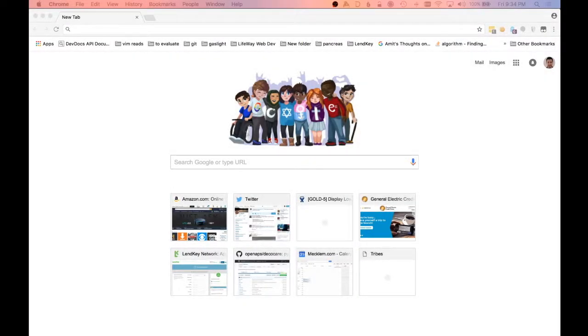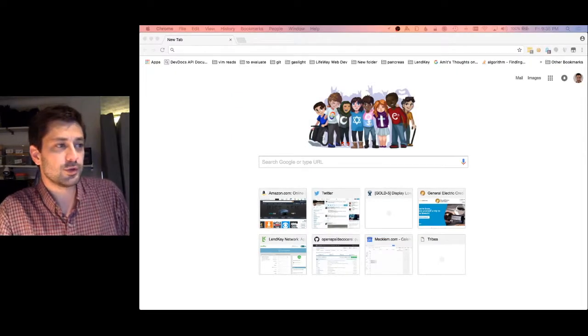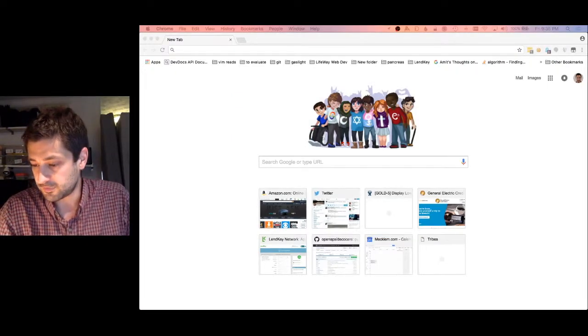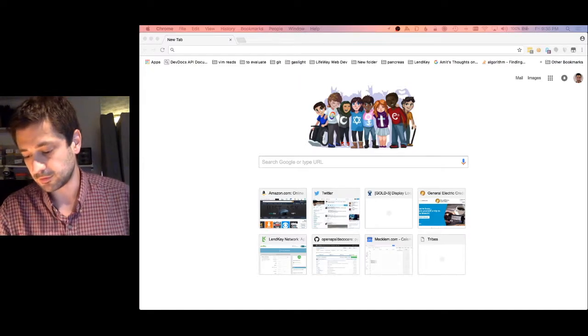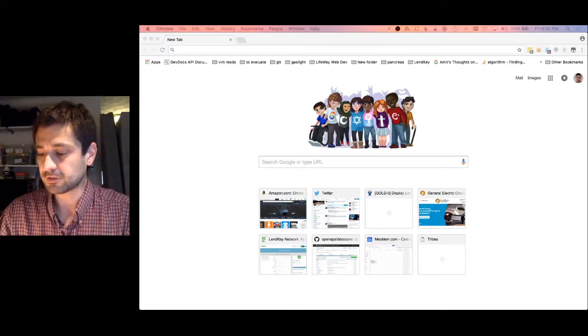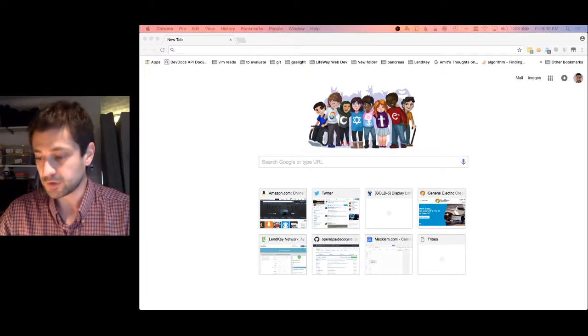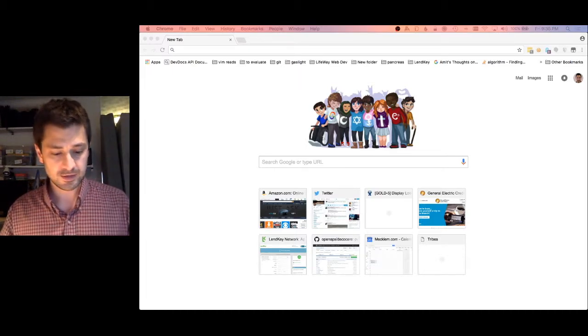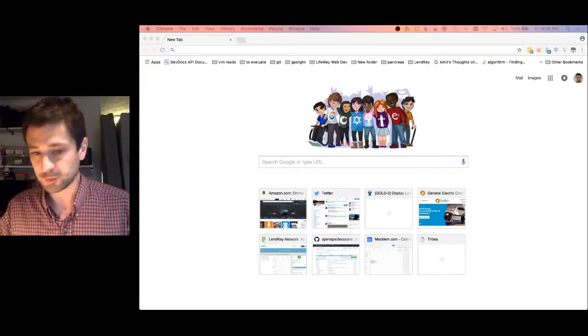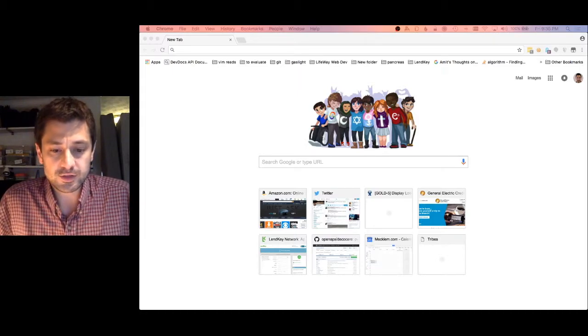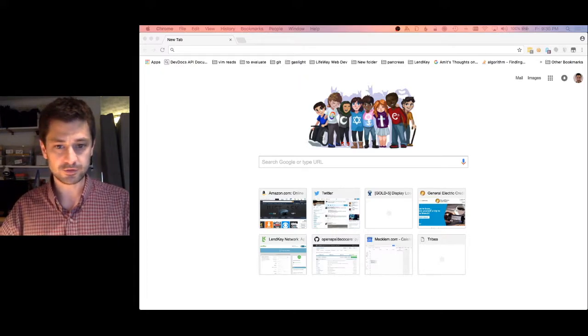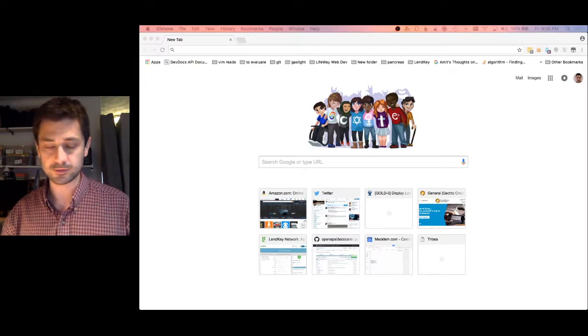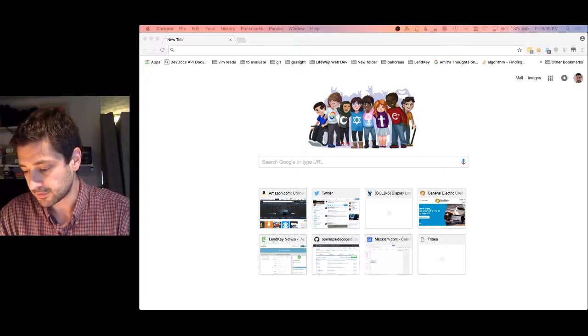What I've been working on for the last 2 weeks or so was the idea of building something kind of like a visual of what the pins look like physically on the Raspberry Pi, and you can manipulate them within the application and set them to input or output and read or write to the pins. And I wanted to make it skeuomorphic, to borrow a term from mobile device development, so that you can see the pin on the screen and see the pin in real life and make a relationship mapping between the two so that you understand what's going on.